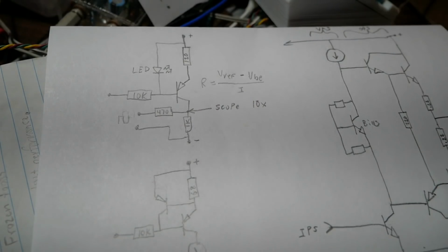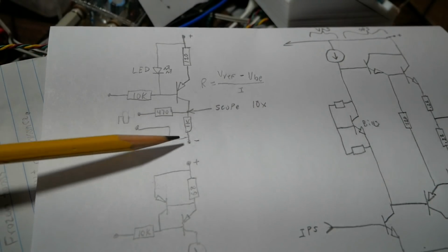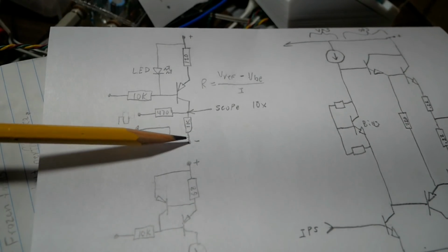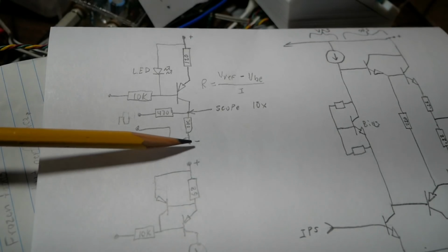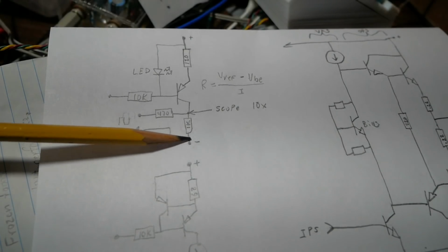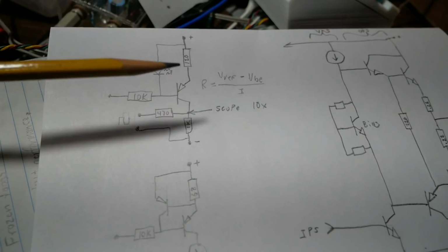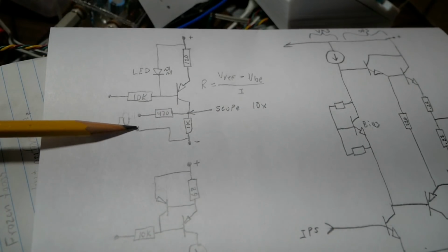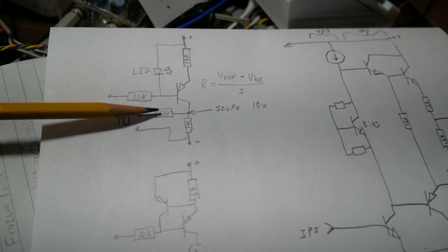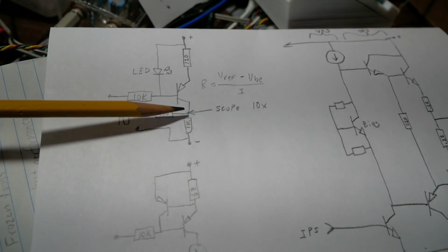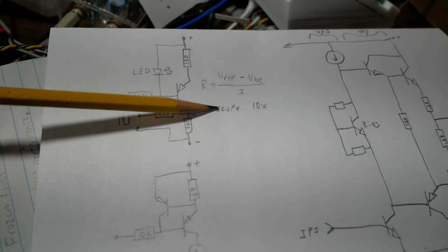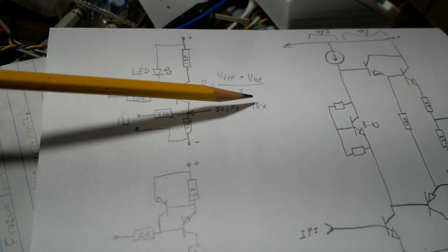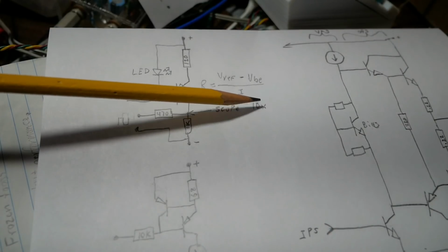Okay, I'm setting the circuit up for the dynamic signal test. So I'm injecting the supply 32 volts, or I guess you can correctly say negative 32 volts, through the 1K resistor. And now the signal generator is coming in on these leads through a 470 ohm resistor. And at this point I'm going to use the scope to measure the signal, taking care to set the probes of the scope into 10x mode.